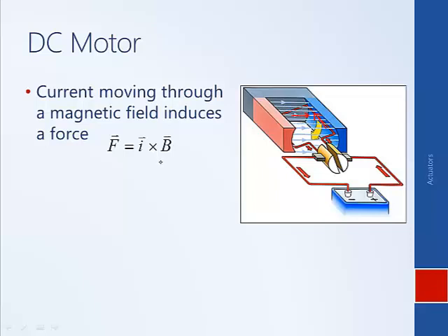For this cross product you can determine the direction of the result using the right-hand rule. So you cross the current vector with the magnetic field vector, and the force will push down. So on this little segment of wire, there'll be a force pushing it down. As the current flows around the circuit, on this side of the circuit, the current is now flowing in the opposite direction.